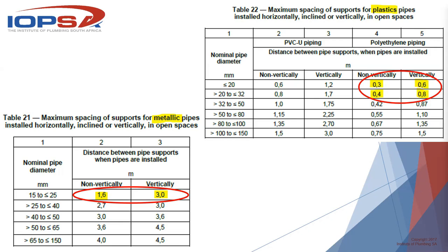thing properly. So when you go and plumb a new house and you get audited, I'm not going to say the word unfortunately, but perhaps some might think it's unfortunate that this is the standard that we have to audit to. This isn't a rule that we choose to make. This is what the standards require. And if we look at it and we see that there isn't pipe supports every 300 millimeters on a 1/2 inch plastic pipe, it's a failure. And that's just what it is. So, and you can see the vertically for a 1/2 inch pipe is 600 mil. So that's dead straight up or down.